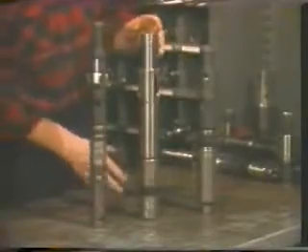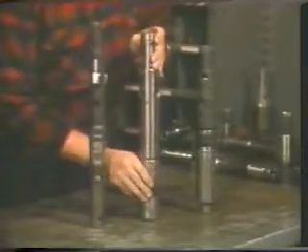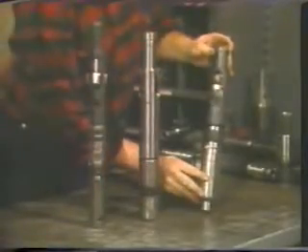One of the most common subsurface controls that is anchored by the lock mandrel is the plug. Plugs fall into three basic categories, depending upon which direction they hold pressure. There are plugs designed to hold pressure from below only, above only, and from both directions.